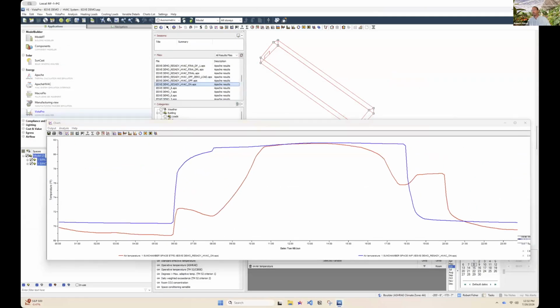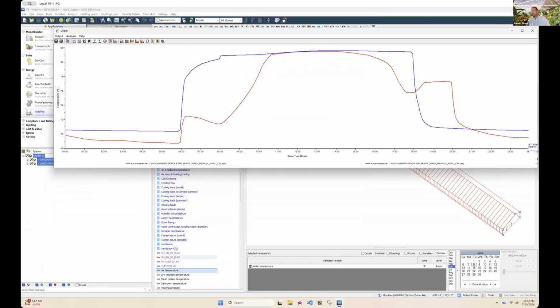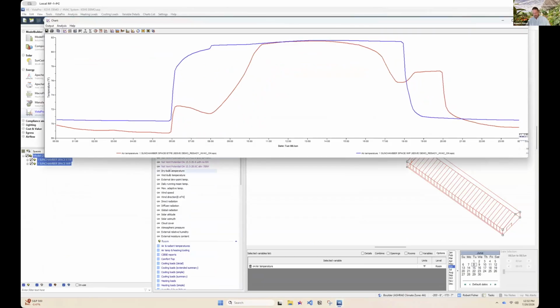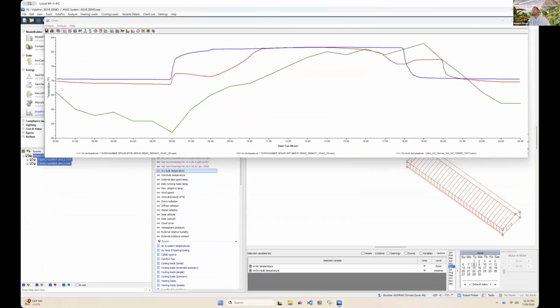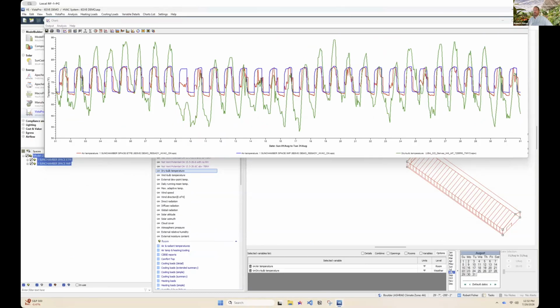We have the weather outside that we can go ahead and pull in here. If I can get to it. So the dry bulb temperature, we can get the dry bulb temperature that's outside at that moment in time. So green is now the outside temperature. And if we go to somewhere like January, you can see it's much colder than the greenhouse and the insulated panel. And then during the hot summer, you can see that the outside temperature is far exceeding.